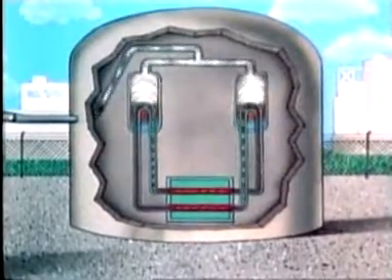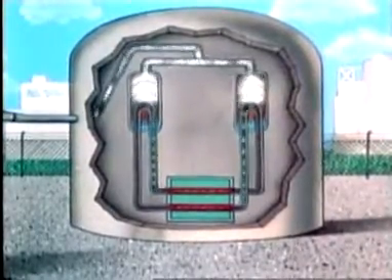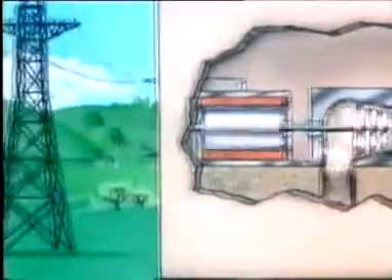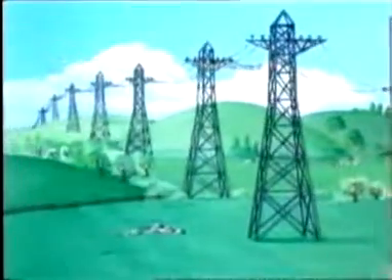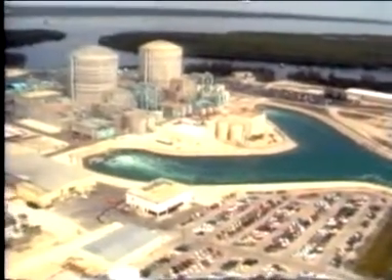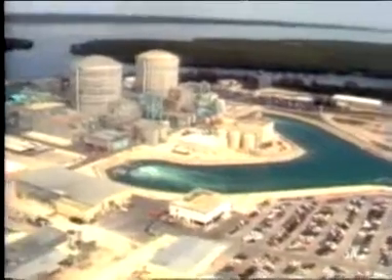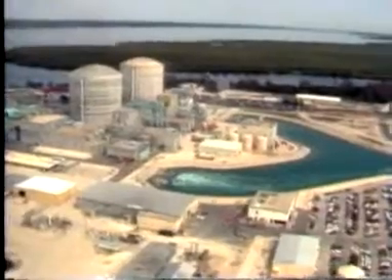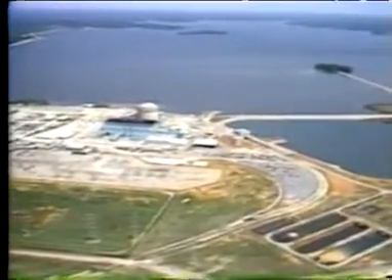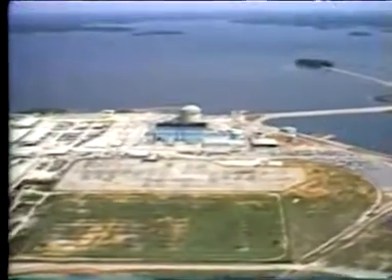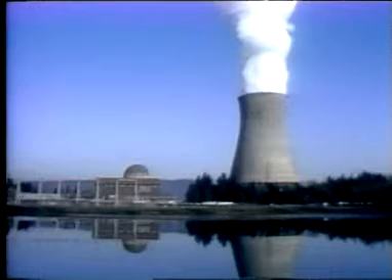A nuclear plant has similarities to a normal coal or oil-fired plant. The fission provides the heat to boil the water, and then steam drives turbines and generates electricity. To generate power, it is necessary to have a temperature difference. Just as important as a hot side is a cold side. So all power stations using steam are sited near a source of cooling water. However, it usually is illegal to warm a river because it will affect the environment.